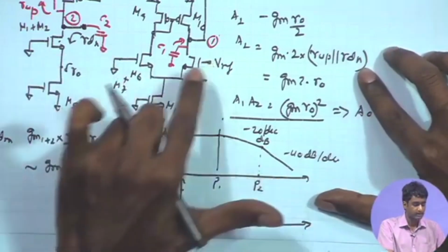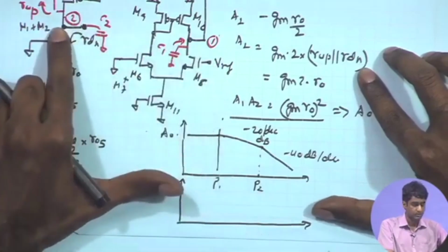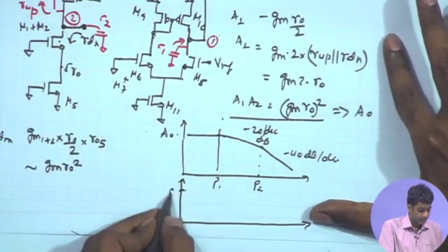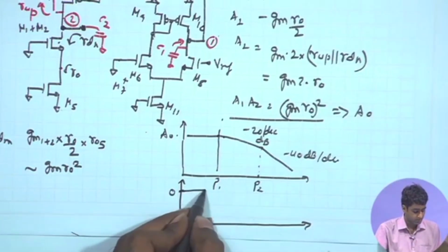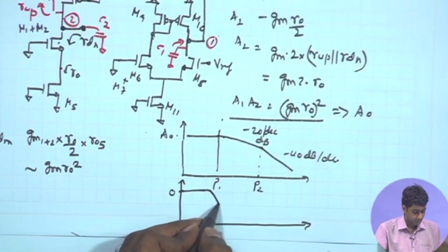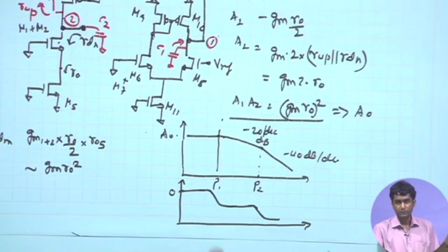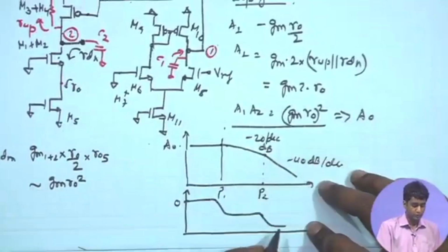Apart from that, if you look at the signal phase from input to output, starting from the very low frequency, ideally it should be at 0. So, we will start at 0 and we know that immediately after the first pole it reaches 90 degree, and immediately after the second pole it drops down and approaches 180 degree, provided you have the third pole lying somewhere close, it will approach 180 degree pretty fast.